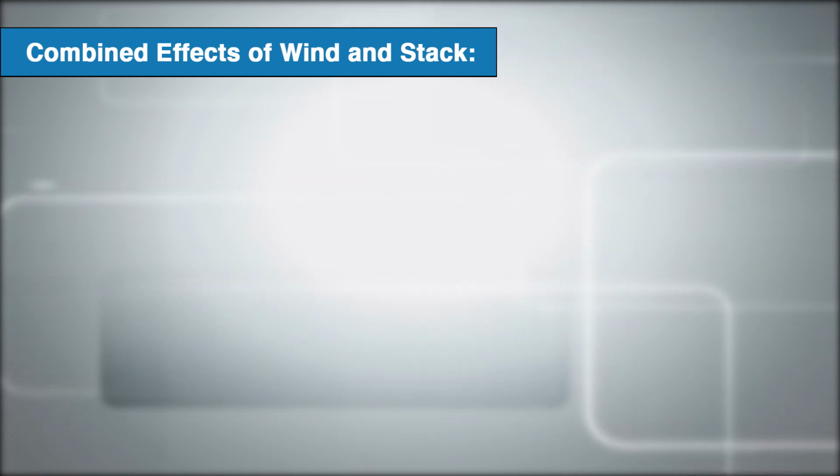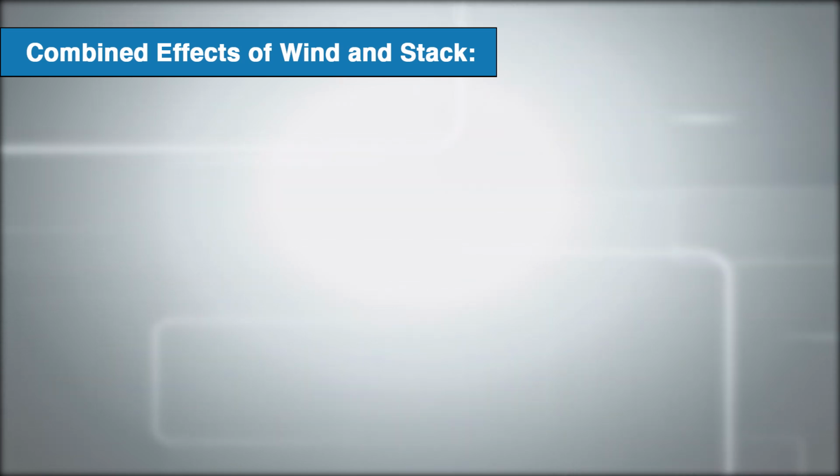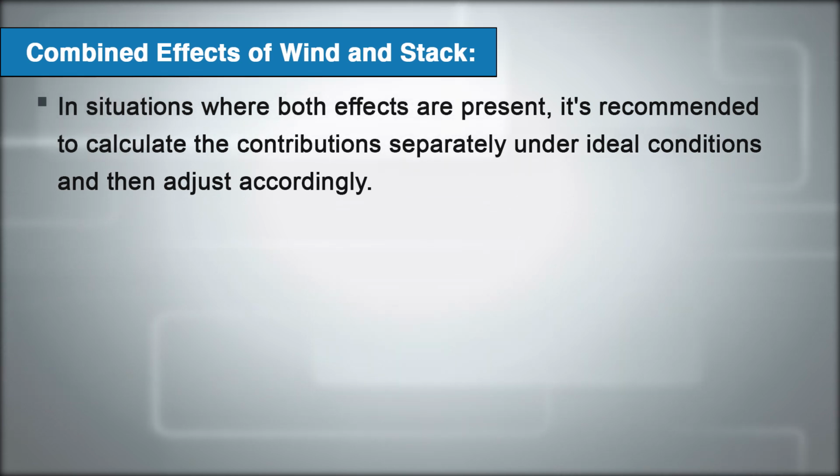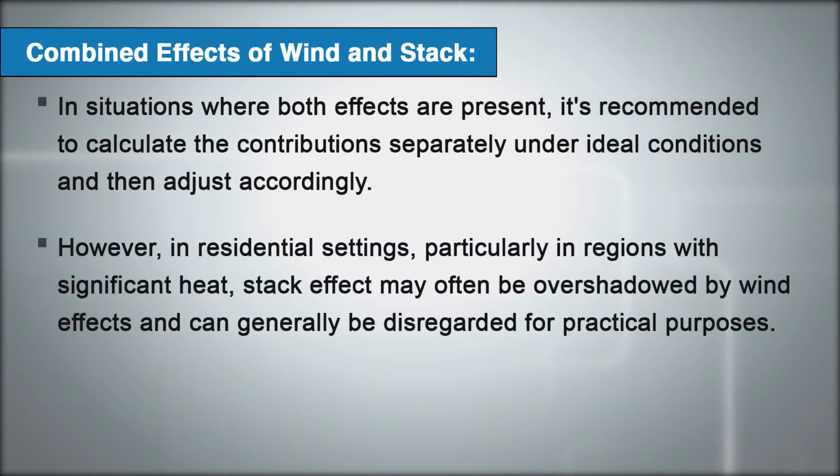Next is the combined effect of wind and stack. In situations where both effects are present, it is recommended to calculate the contribution separately under ideal conditions and then adjust accordingly. However, in residential settings, particularly in regions with significant heat, stack effect may often be overshadowed by wind effect and can generally be discarded for practical purposes.